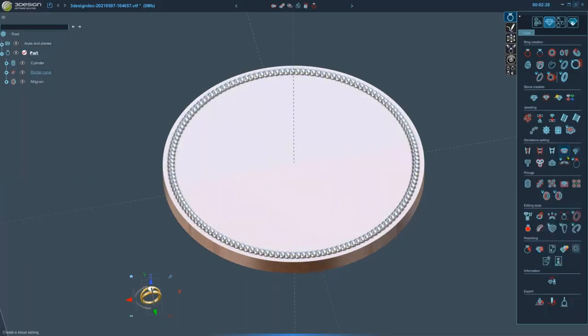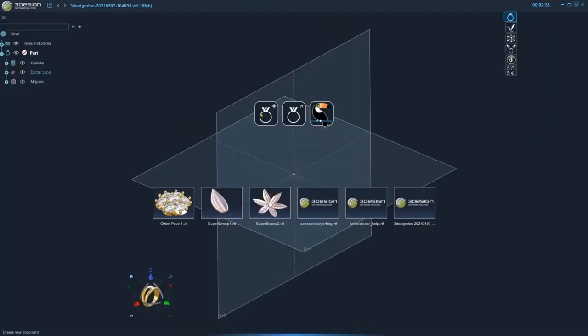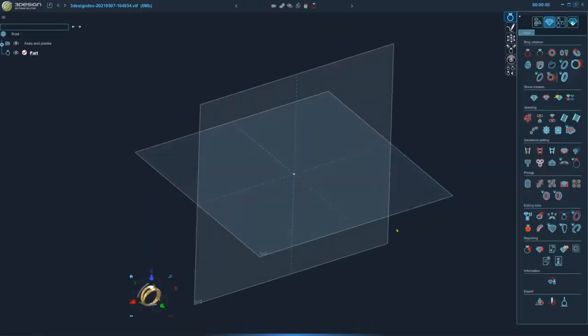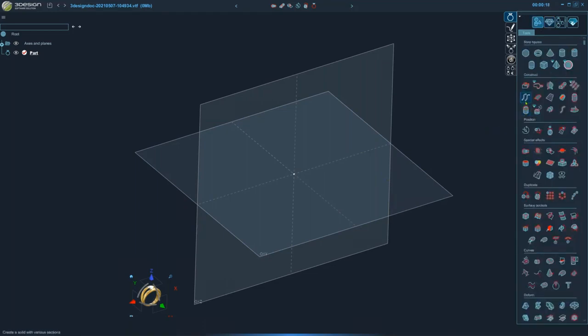All right. Next up, we have another interesting one, this super sector, or I don't know what we're going to call that exactly. We want to change the name. Circle sector. It's using a circle sector, but it's automatically going to repeat your shape that you're using your circle sectors on. Circle sectors are complex tools, and not a lot of people mess with them. So this one's going to make it a little easier. I just want to take an object, and this isn't necessarily for a ring, but I want it to go around an axis. So maybe I'm putting it onto a wedding band or something.